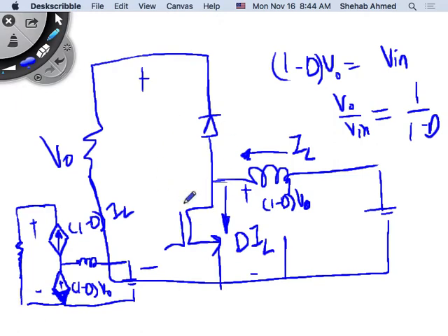I took my circuit, which has switching elements, which are nonlinear, which are not part of what we design controllers for in 420. In 420, we design controllers for linear time invariant systems. Linear systems do not have switching elements. You don't switch voltage between one condition and another. Linear circuits typically change voltages or current in a continuous fashion. There's no discontinuities. Once you have discontinuities, then it's really a nonlinear system, and if you want to use linear control, you have to figure out a way to represent it as a linear circuit. And that's our approach.